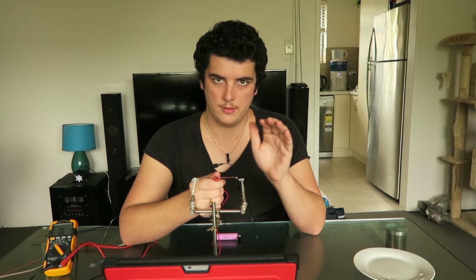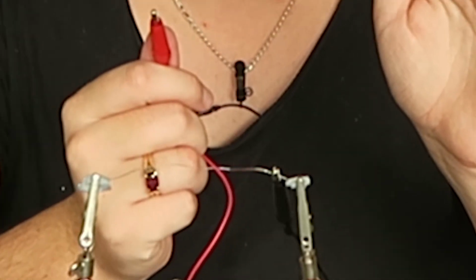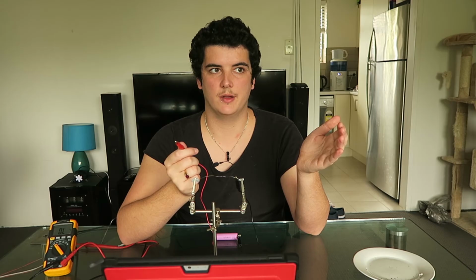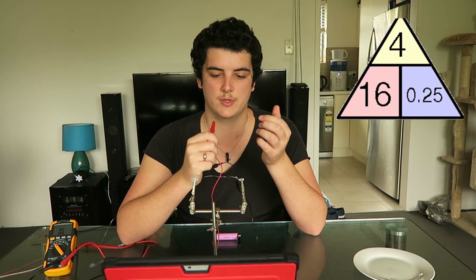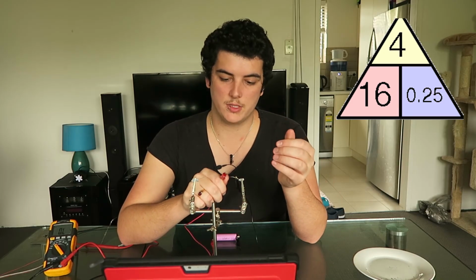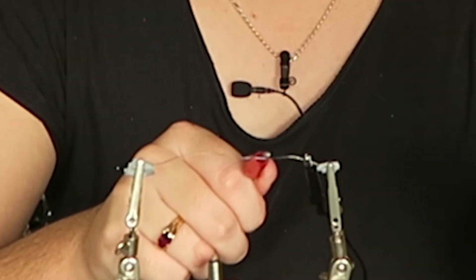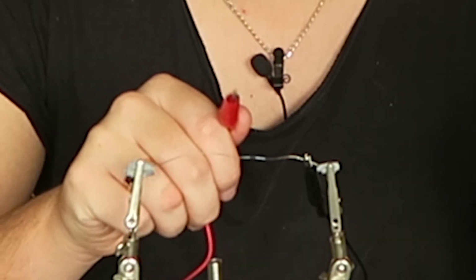Okay, you can see that starting to glow, right? That's red, that's hot. If we go a quarter, that's about 250 milliohms. So therefore we should be getting about 16 amps, which is very bad for the cell, but it's only for a burst, so it should be fine. Now watch how quick this lights up. See that? See how quick that glowed?